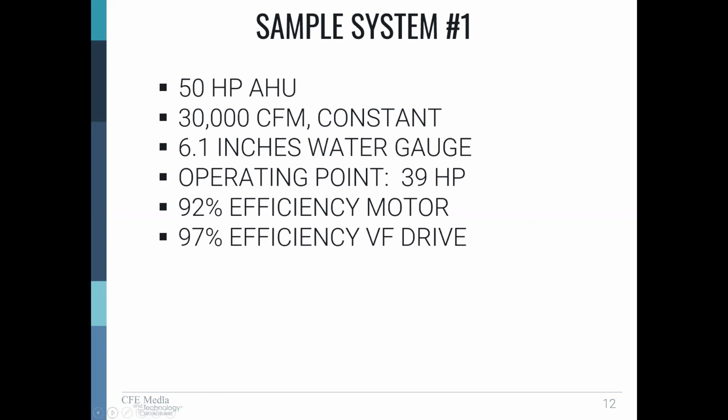Typically, high efficiency motors operate around 97 or 98%, so you have a drop off in motor efficiency due to it operating at a lower speed. And then the VF drive at this particular point is about 97% efficient. The electrical load for this, by the time you go through all the numbers, turns out to be about 32.6 kilowatts.